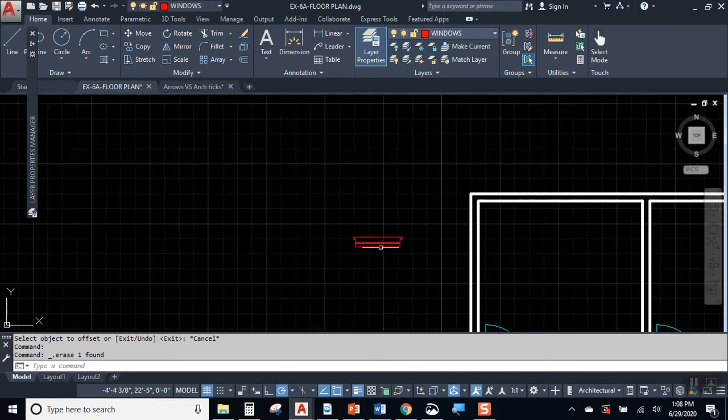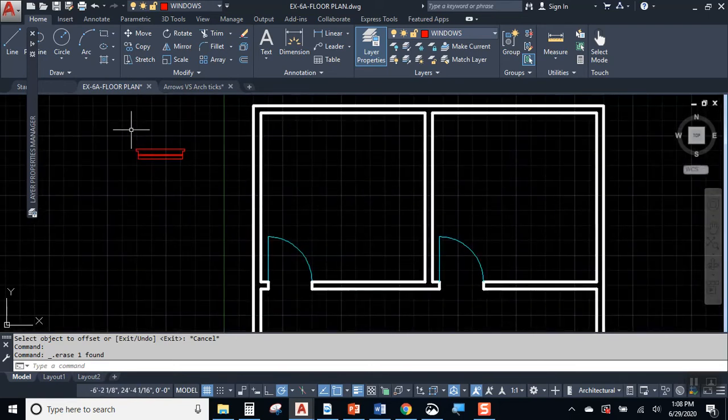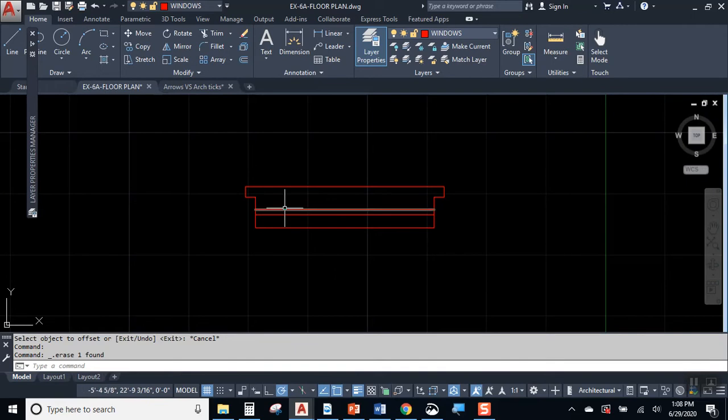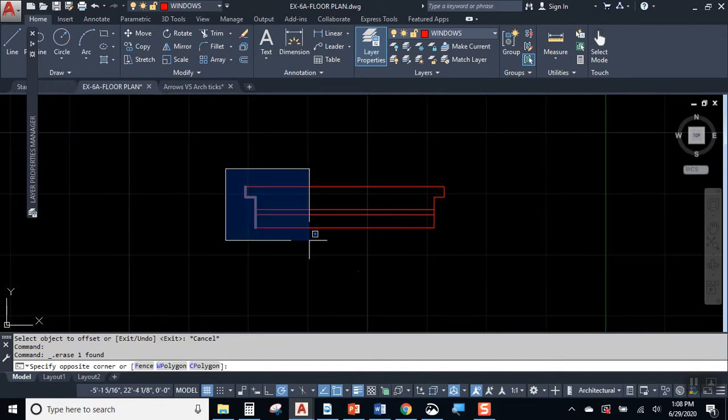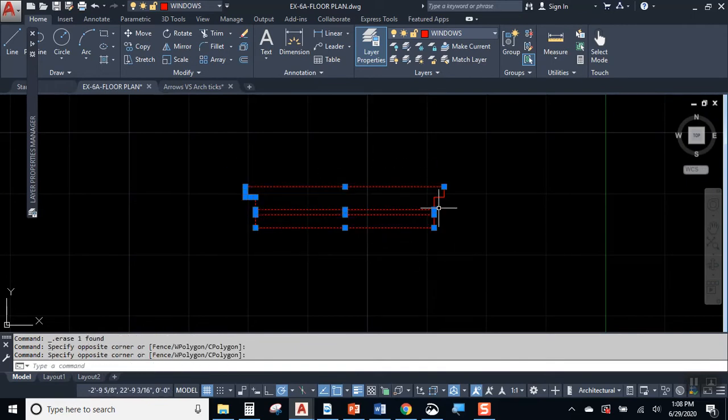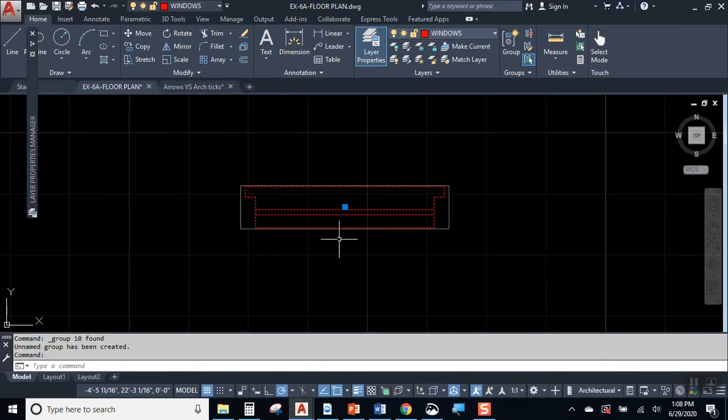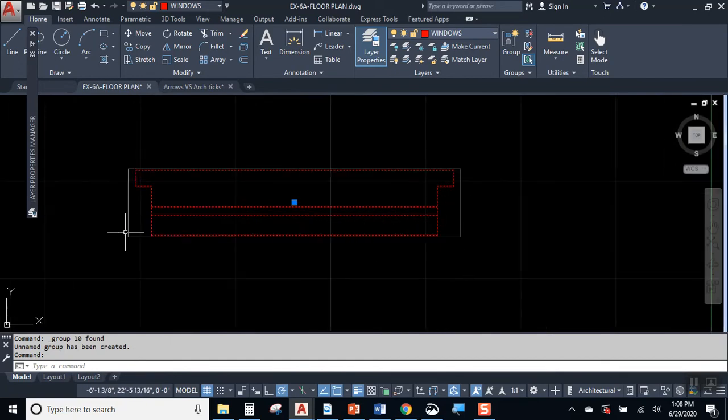We're going to use it several times on this drawing because there are several windows in this project. So what we're going to do is, instead of having to select everything every time and wondering, oh, did I get all of it? Let's just make a group. We'll turn our window into a group. All right, and now I've got it in a group. You can tell it's a group because it has a white gray box around it and a grip in the very center.